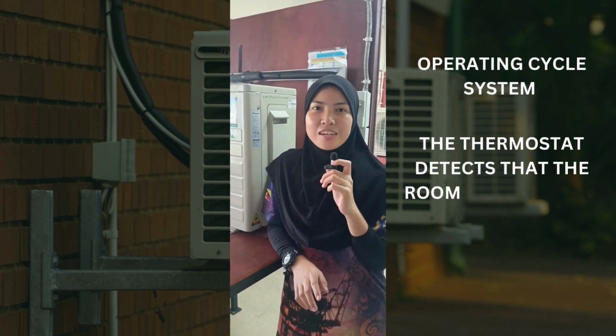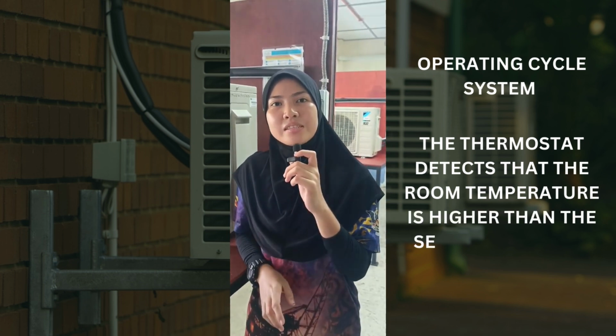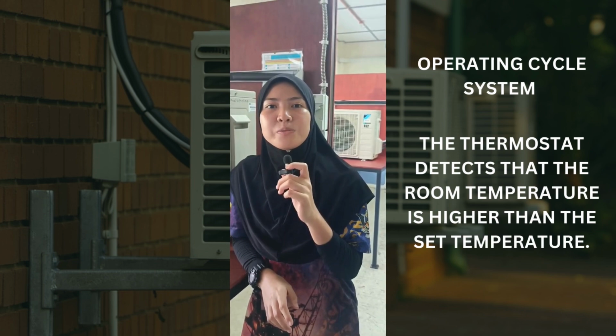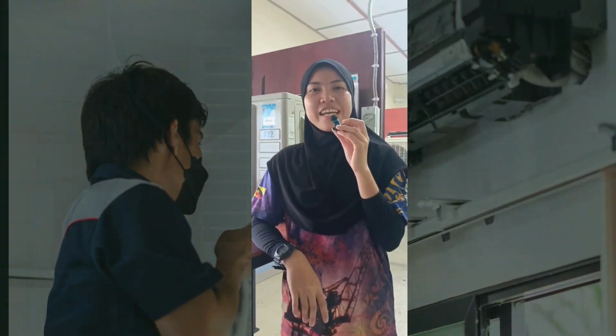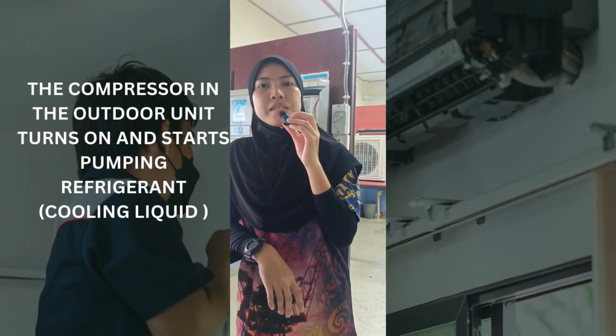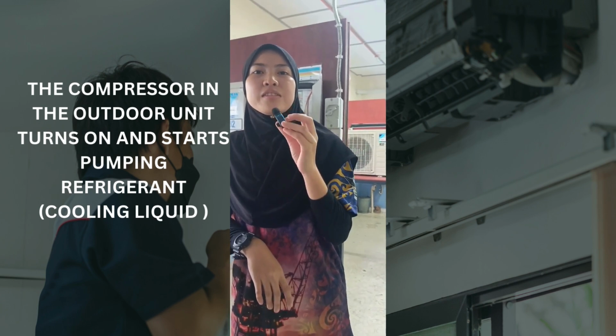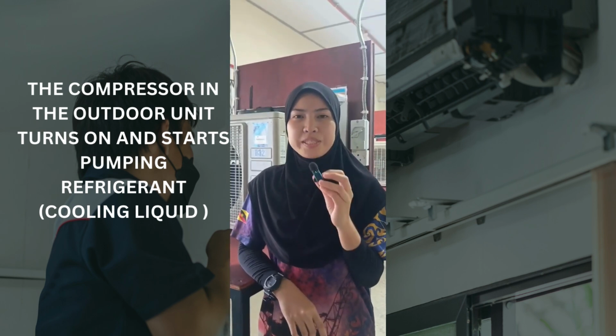When the air conditioning is switched on, the thermostat detects the room temperature is higher than the set temperature. Next, the compressor then begins to operate. The compressor in the outdoor unit turns on and starts pumping refrigerant, the cooling liquid.